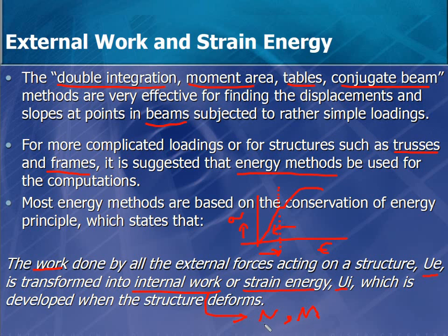And sometimes, in a beam or a frame, if there is no lateral load, we can neglect the normal force. We can explain this with an example, to show when it's possible to neglect the effect of normal force on deflection. So we're going to discuss both of them to see. Now this is the idea when we said it can be used for all the types of structure we have, the beam, truss, and frame, because we have internal forces in each of them, and we can use the idea of external work and internal energy for all of them.